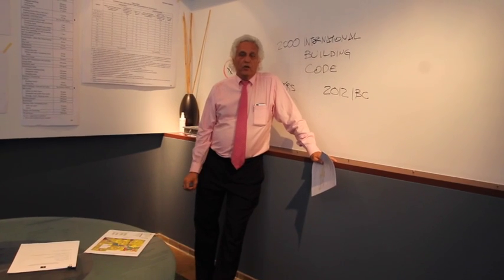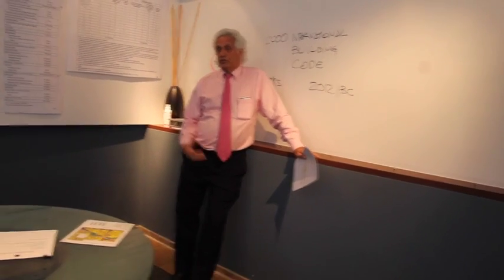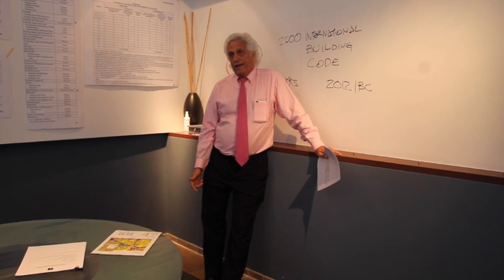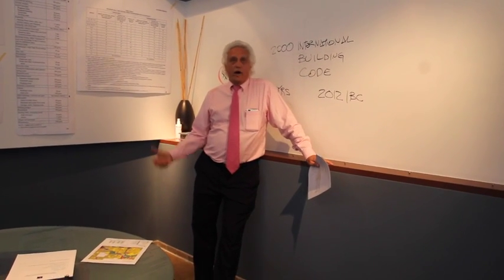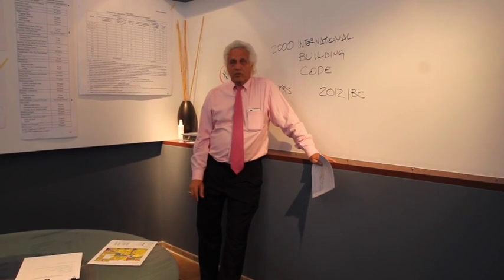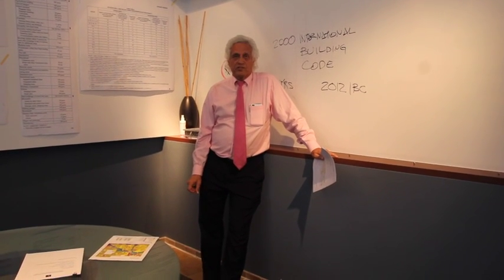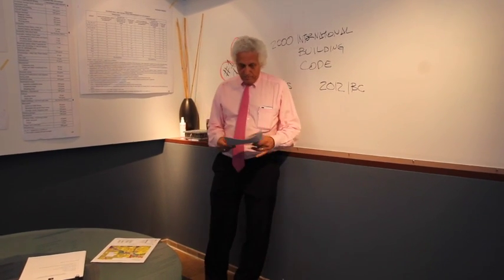Whereas in the UP, you're designing the roofs for about 90 pounds a square foot. Is it reasonable then to add a snow load in this part of Michigan for 100 pounds a square foot? No, because we would never approach that. So again, it's the reasonably safe requirements, not the most safe design on the building.